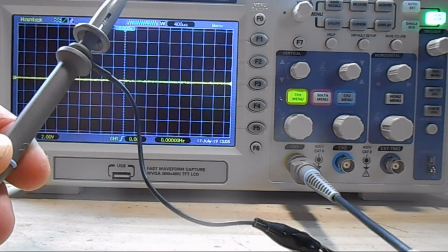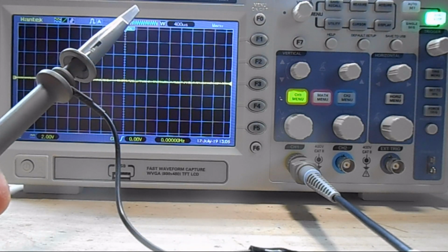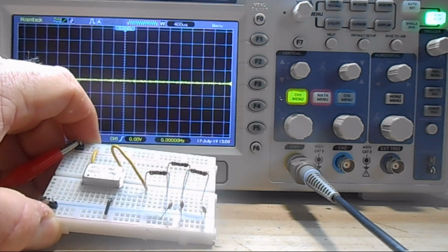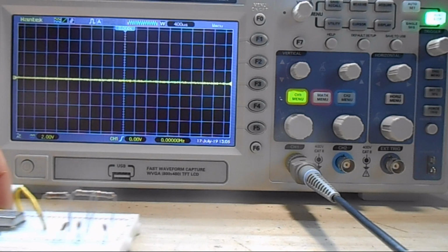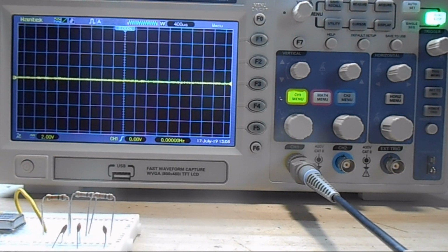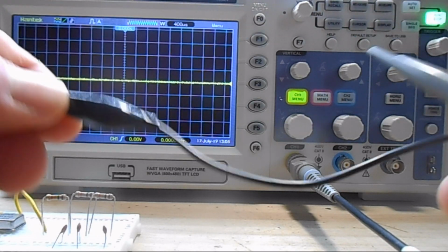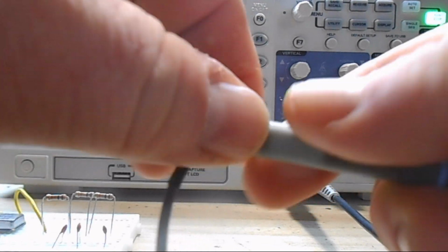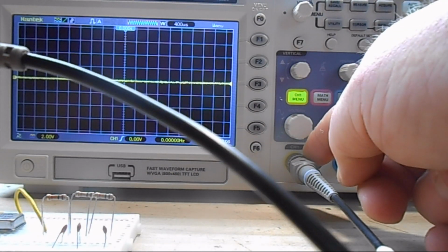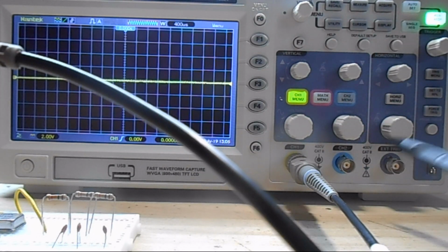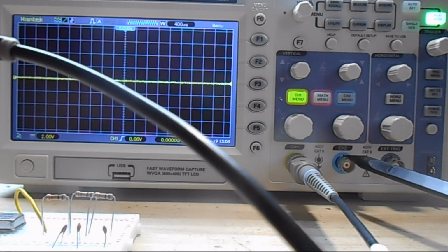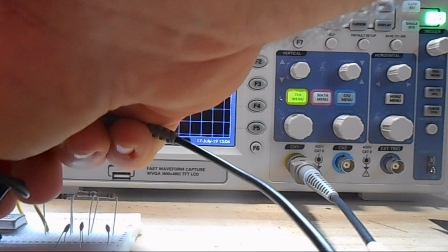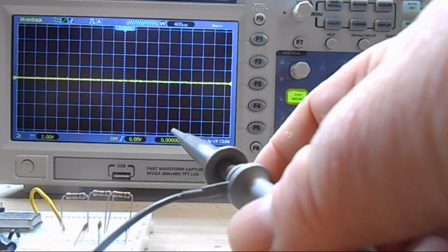Now one thing that we definitely want to talk about here is probe usage. Here's how we're getting our signal on the screen. This is a 10 megahertz crystal oscillator. So we're going to connect up to it, and we're going to connect our ground first. Now this ground lead that you see here is connected to the outer shield of this wire, which is connected to the outer part of that BNC connector. That right there is a direct short to your household ground. You definitely want to keep that in mind, or you'll blow stuff up.